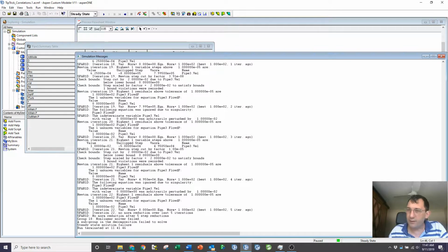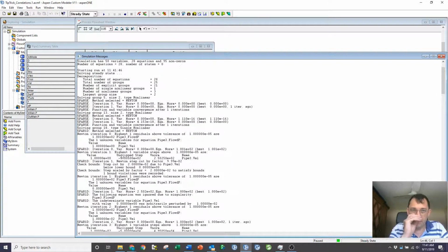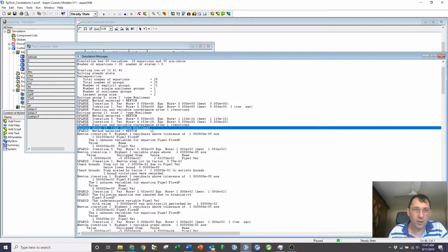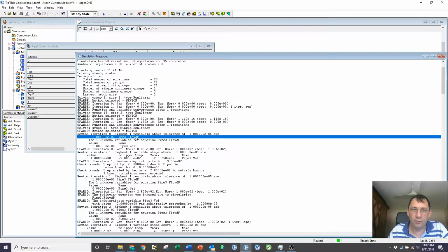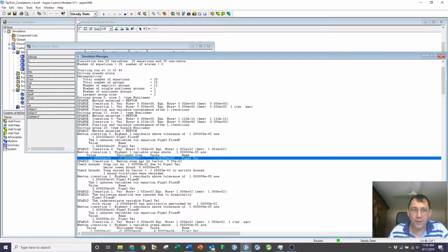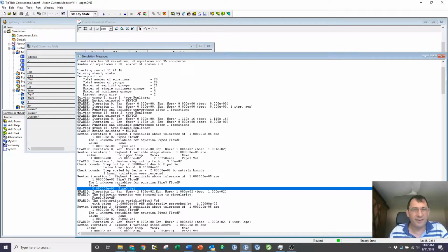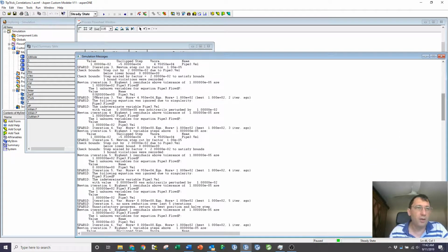And again, it fails to converge. That's irritating, isn't it? Why is that? Well, now we can come back up and we can have a look. And we can see that what's failing to converge is this single nonlinear equation, rather than being a set of 5 equations solving simultaneously. And what it's saying is that DP flow is really something I'm not happy with. My velocity starts off at 1, I'm trying to force that negative. It hits the bound of 0, it's still trying to force it negative. So there's definitely something touchy about that DP flow equation.